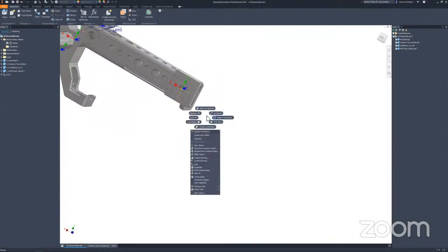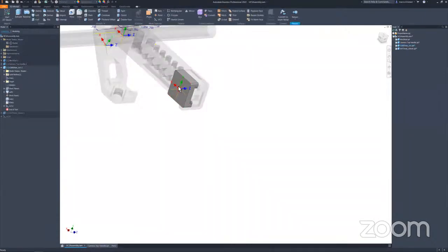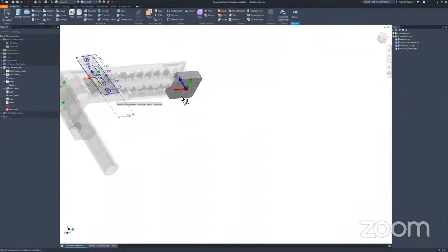Nice. Yeah, that's a really common question we get in Inventor. Can I change my universal coordinate system in my part? Which largely is no, but you can do this thing with the custom UCSs, where you can just define a new center point for your part and then constrain it to where it needs to go. That's a really common one, yeah.